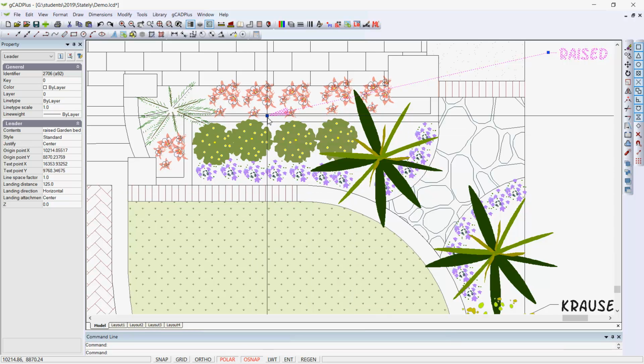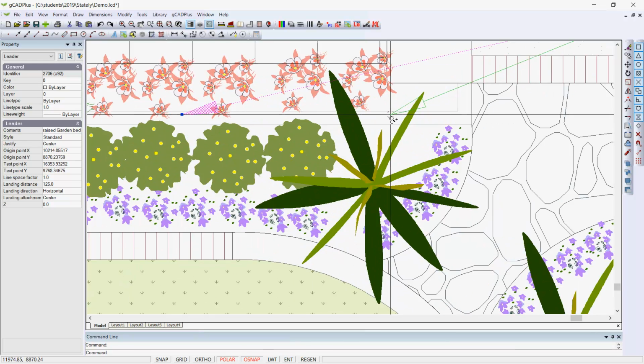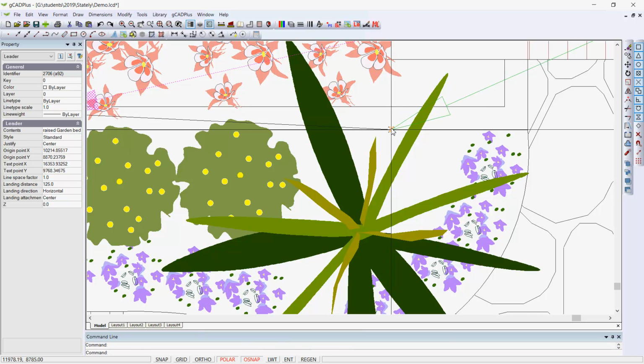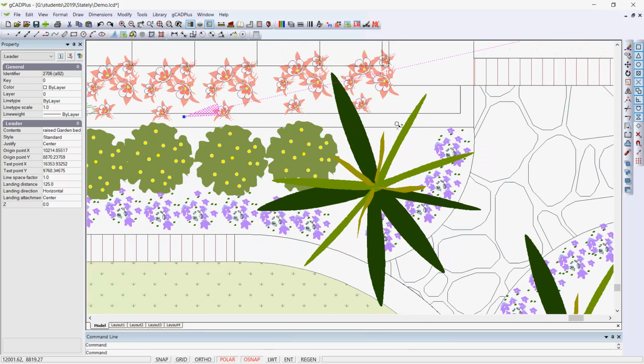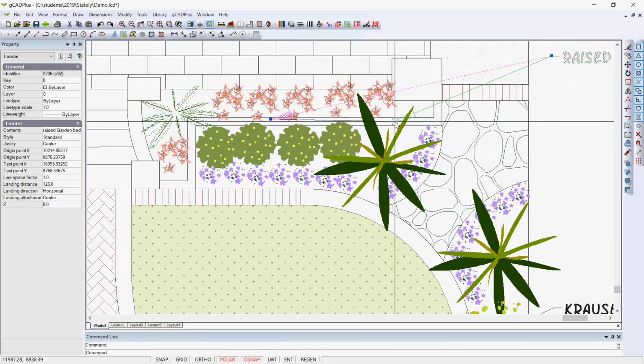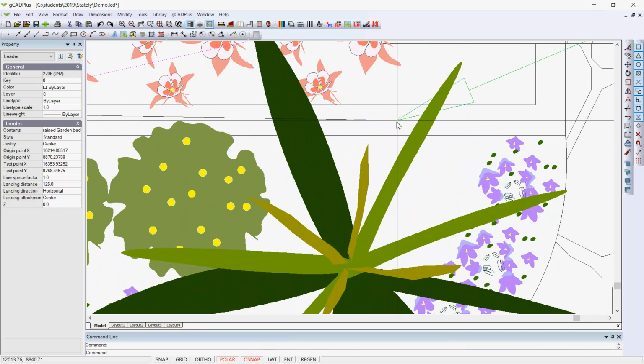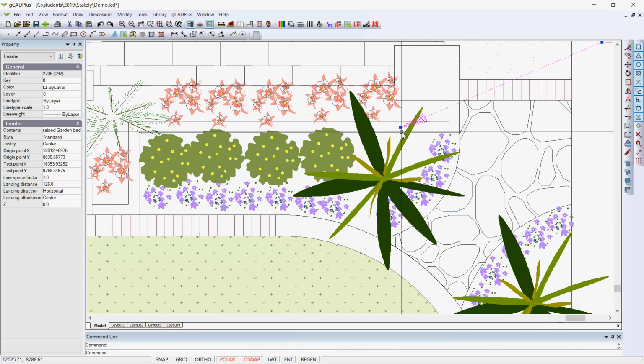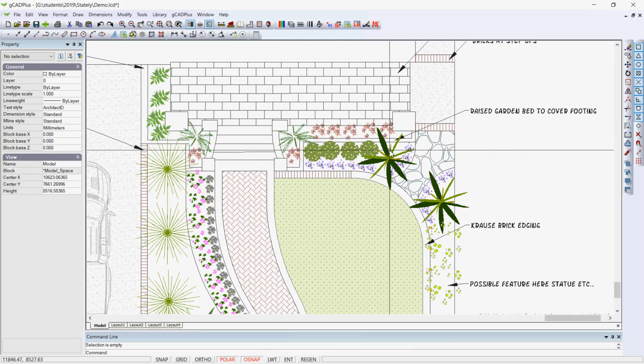I want to move the arrowhead over here, and I want to be halfway in the wall there. You can see that as I move it, because osnap's on, it's jumping to nearest all the time, and in order to get the pointer to pick the middle of that wall, I actually have to zoom right in and do that. So it works, but there's a little bit of extra work to do because those settings are on all the time.